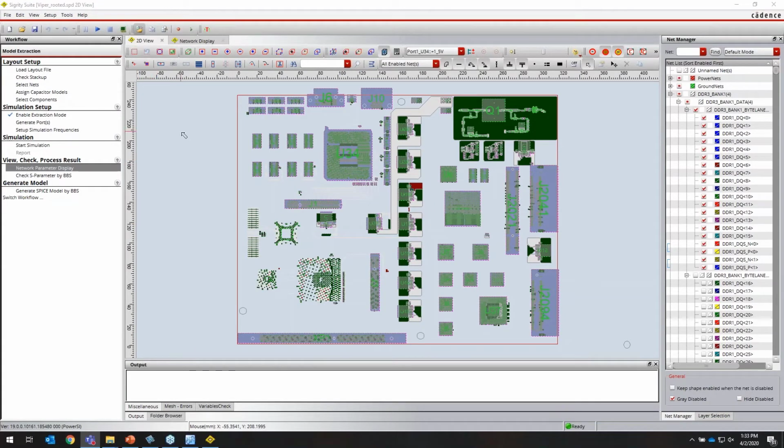So this is the same board as Orland mentioned. I've loaded this up in one of our signal integrity tools. The point here of what I'm going to do is to do the simulations. Essentially, you need to first extract models of the parasitics of your layout. All the layout work you did, you need some type of model that represents any of the delays and coupling interactions and things of the signals. We are interested in this section of the board right here, so that's where I'll zoom in and focus my attention.